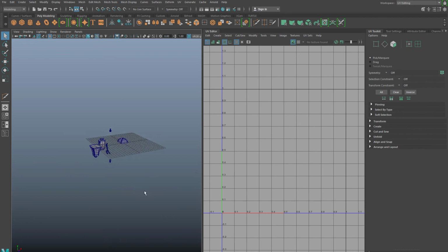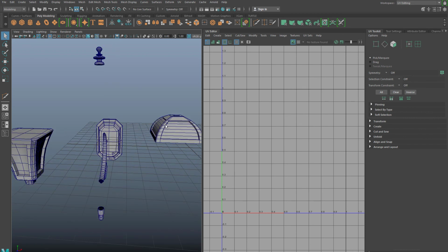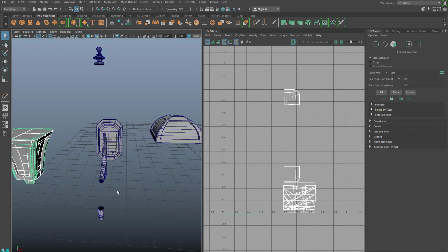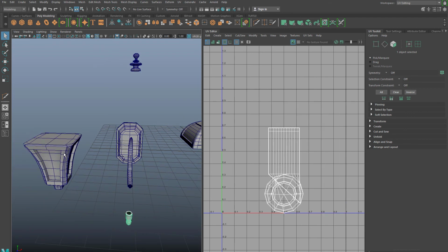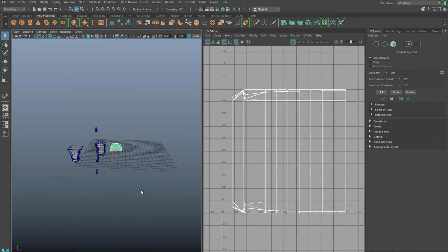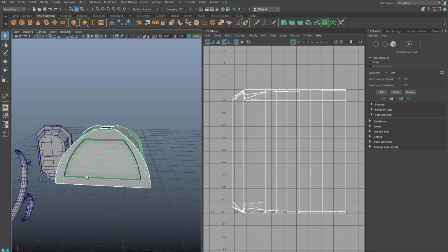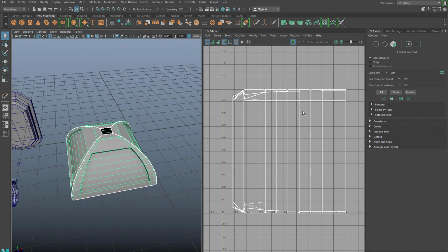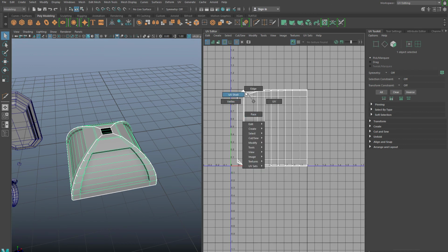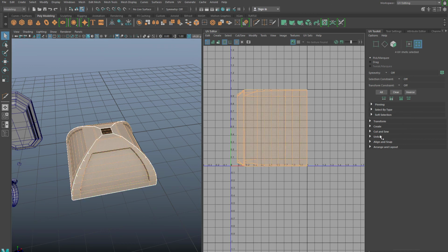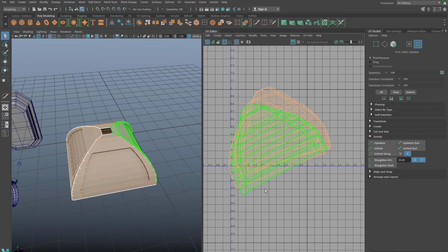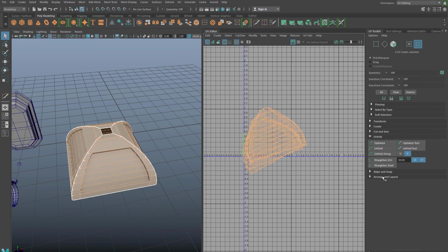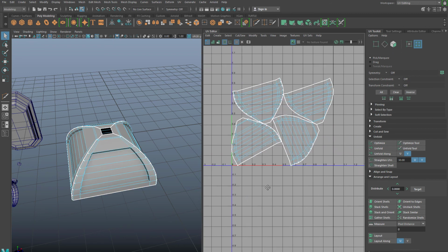So here's my parts, and they are going to need UVs in the worst possible way. Real quick, easy on looking at this. Let's see what happens if we just go to UV shell, select everything, and do an unfold on it. Okay, well, that doesn't work out so bad. Lay it out. Got my sections.